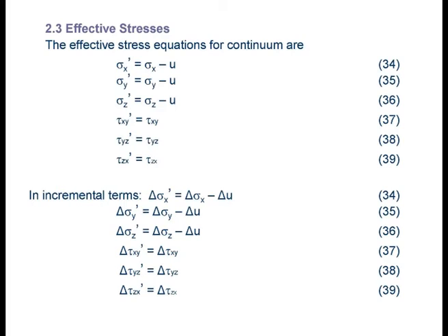Similarly for sigma z. Now, when it comes to shear stress, and this is something, I'm afraid to say, a lot of textbooks skip, and when I teach undergraduates I don't teach it either, so students come out totally blank on this part. But in fact, when you deal with shear stress, there's no effective stress because water cannot carry shear. Water has zero shear stiffness, it cannot carry shear. So the effective shear stress is always equal to the total shear stress. In fact, we don't even mention effective shear stress. We just take them as one and the same thing.